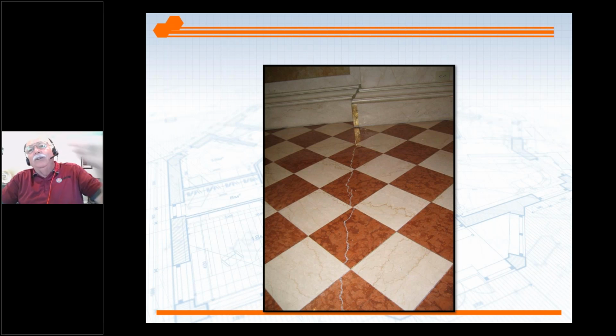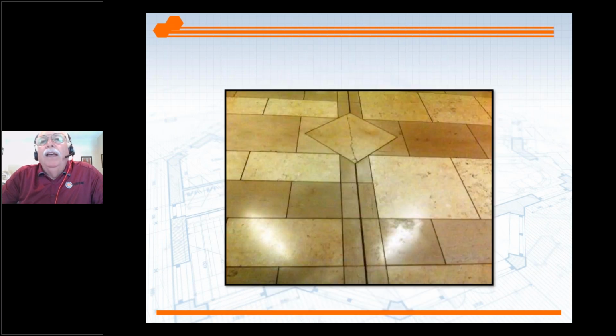This is a casino out in Vegas. Out in their parking lot or maintenance facilities, they have an extra pallet of both colors of these stones, and they actually replace these pretty quickly. The engineering firm put their soft joint in, but they really wanted to keep that design pattern without that soft joint going through the middle of that diamond pattern there. But of course, the structure still decided to place that movement joint in.